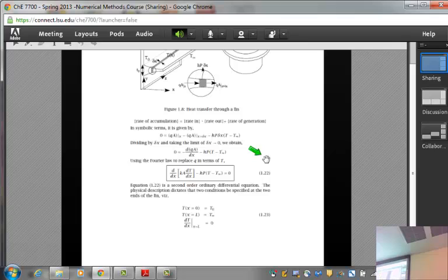So one is to say that the tip is as cool as the ambient temperature, it's T infinity. The other one is the tip is so thin that the flux of energy out is equal to 0. But the tip could be hot, and I don't know what the temperature is. So that's a well-posed problem, a second order equation with two boundary conditions, a couple of variations on the boundary conditions. We will see how to solve each one of those variations.